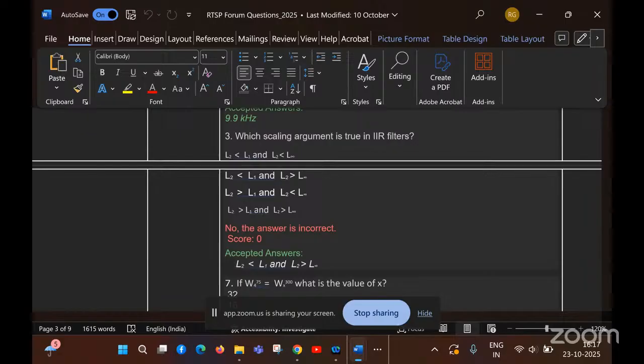In an IIR filter I can use parallel structures, but in a parallel structure it becomes an addition and may overflow. Hence we use the cascade sections. I think I made it clear when I took the IIR filter how you organize second order filters, and if there are more than two, how you organize them. So the L2 norm is what we calculate with the pole positions.